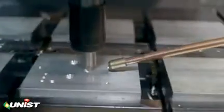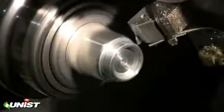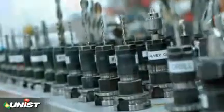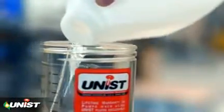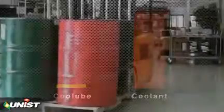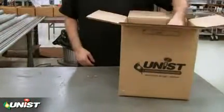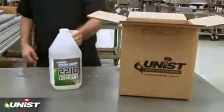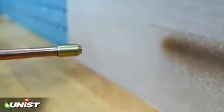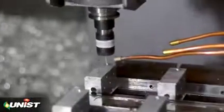MQL is so effective at lubricating the cutting tool that heat is no longer an issue. With MQL, you can rest easy knowing that your cutting tool investment will last longer. One of the best things about MQL is how small an amount of lubricant you need. Gallons of flood coolant are required for an 8-hour shift, compared to only a few ounces of Cool Lube lubricant. When you consider how little Cool Lube is used and the fact that no additional fluid circulation equipment is needed, Cool Lube quickly becomes drop for drop the most economical fluid choice.